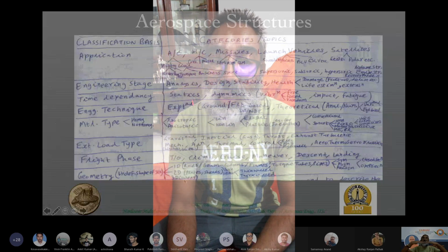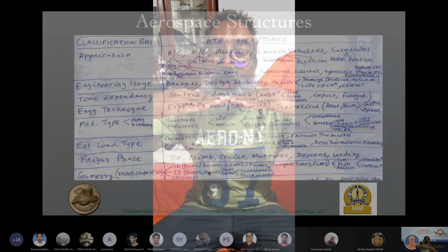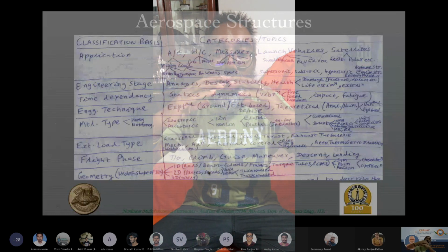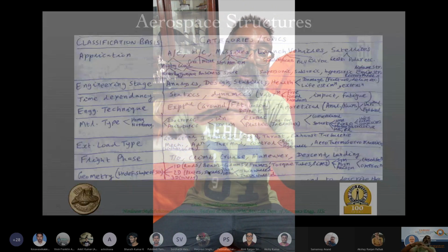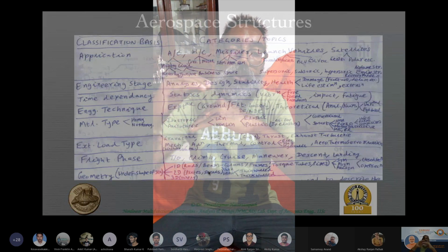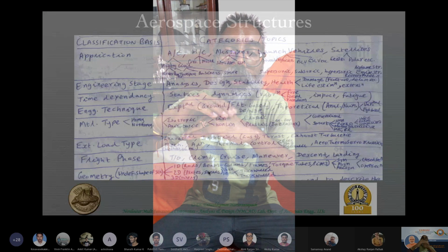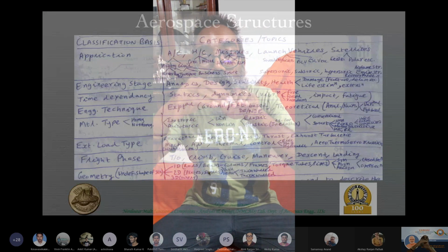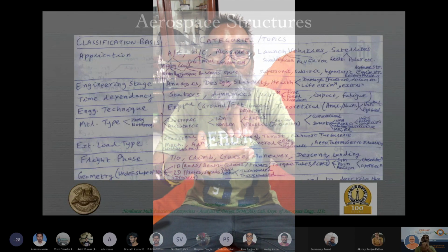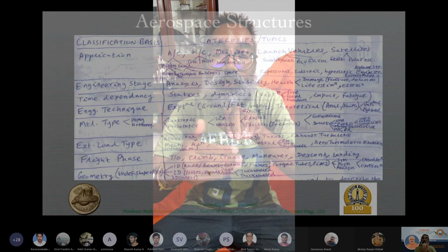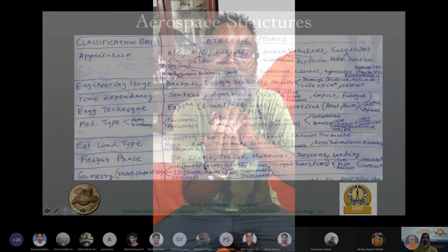And again, when it's 2D, if it's not having any initial curvature, then you can deal with it as a plate, much simpler. And if it is having an initial curvature, like on the aircraft wing, the top surface is basically an airfoil surface, or it is curved. So each panel might look like it is almost having zero curvature, but there is a small curvature. In some cases, like in the leading edge of the airfoil, there might be a very large curvature, and so you do need to deal with these initial curvatures as well. That is, in the unloaded situation, it is curved. That is why it is no longer a plate but a shell.